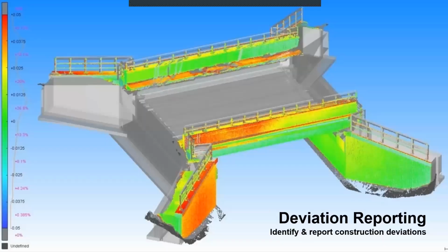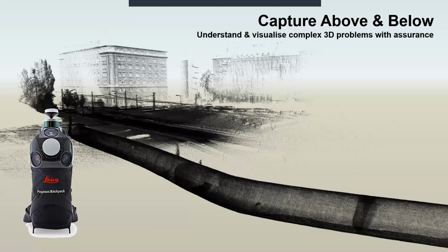In the case of existing structures like heritage buildings, construction bridges, or buildings that are very critical for our analysis and are under the threat of movement or the impact of environmental factors, we can do deviation reporting with repeated scans of today, after 6 months, after 12 months, and then compare that data with the BIM models to understand if there is any movement in the buildings after a seismic activity. Year on year mapping, for example of a 50 year old building, shows what the changes are if it starts deteriorating. In cases like the Lebanon explosion, it shows how it impacted all the nearby structures around the buildings. So we can do all this deviation analysis and reporting for the structures.